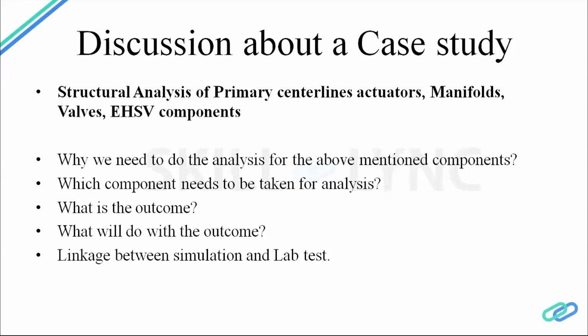Once you establish the linkage between the lab test and your simulation with agreeable margins, then you can proceed with different iterations for design optimization or any other mechanism you want to follow. These are all the basic things that need to be done in simulation.